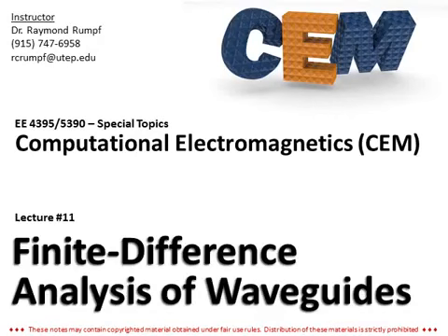This is the first lecture, now that we've cast Maxwell's equations into matrix form on the Yee grid, where we can pull this together and model something. In this case, we're going to be calculating the modes in arbitrary waveguides or transmission lines. The examples I'm going to be using are dielectric waveguides, but they could be metallic rectangular waveguides or microstrip transmission lines or just about anything.